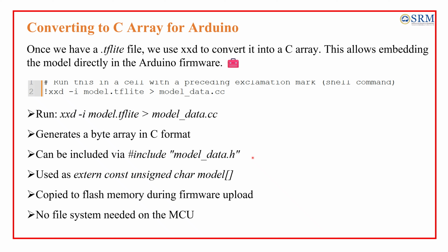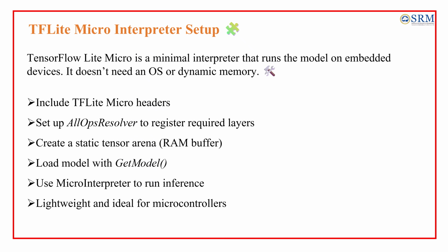Now that model.cc is formed, we need an interpreter on the device to run it. This is the TFLite Micro interpreter setup. TensorFlow Lite Micro is a stripped-down interpreter designed especially for embedded systems. It doesn't need any OS or dynamic memory, and it's perfect for tiny microcontrollers.